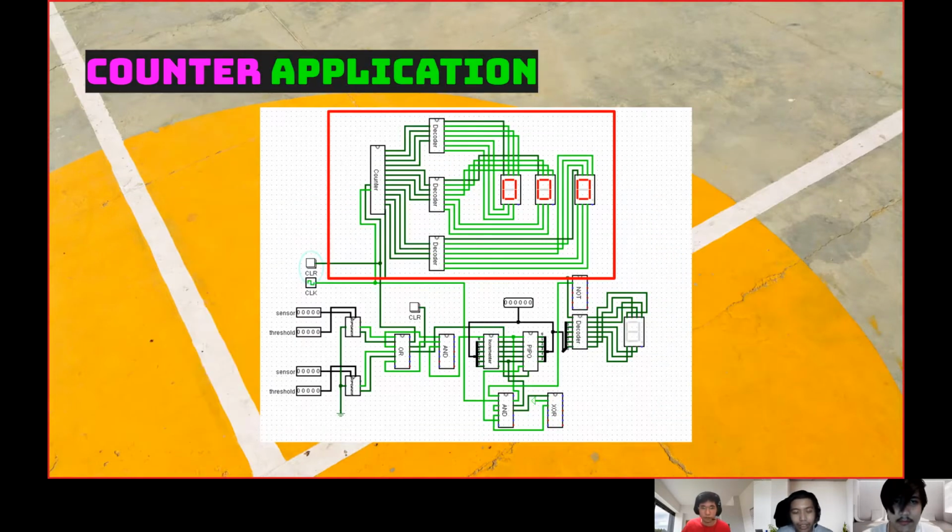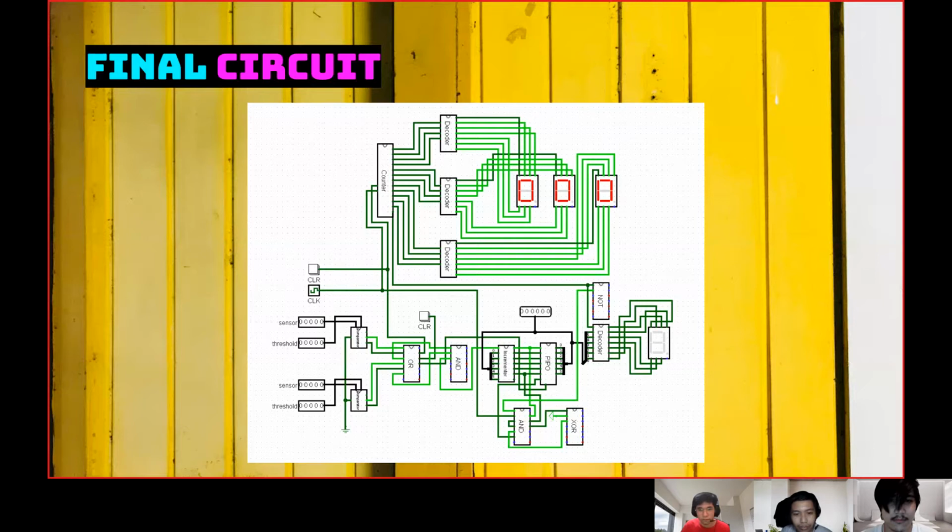There you can see in the top left the counter circuit that was displayed earlier, and each BCD output is wired to its corresponding 7 segment decoder. So it will convert the BCD inputs into the corresponding 7 segment display signals. And so that's all for the additions to our Project 2 circuit. Moving on, we will see the output simulation in the next slide.